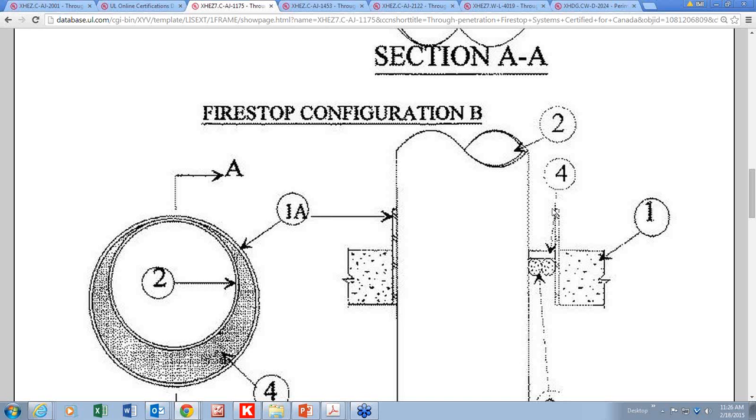That could be jurisdictional or special inspectors that just don't specialize in fire stopping, and contractors that have no idea what they're looking at would miss that too. It's a key detail because the fire dynamics of that sleeve are such that the product may heat up more at the top of the sleeve, might get hotter up here because it's at the highest part of the sleeve. It may heat up sooner than was anticipated, than it would heat up down here.